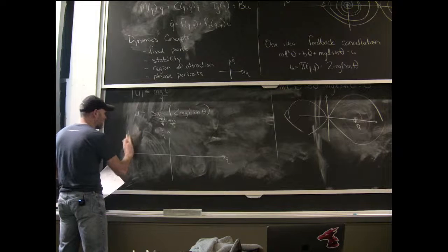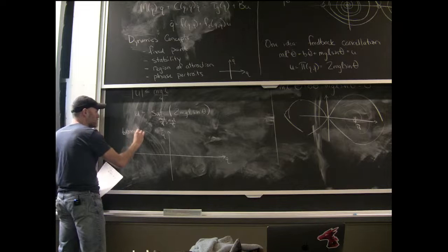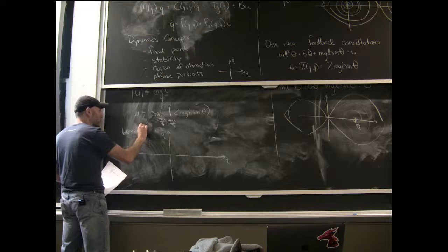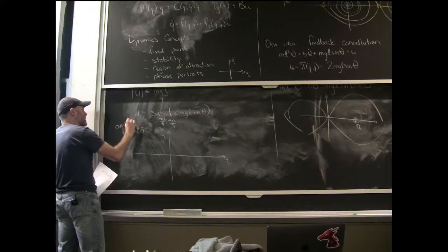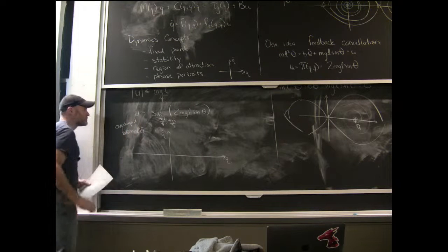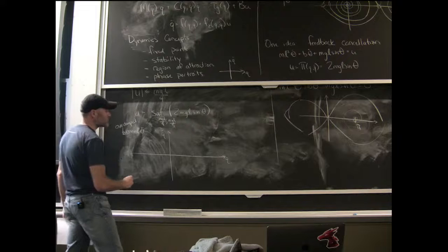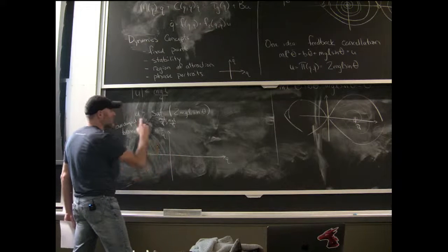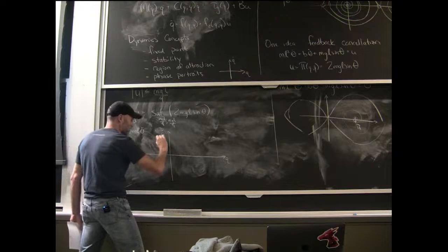So I want to say b theta dot dominates ML squared theta double dot, the overdamped regime, where I could draw this as just a first order plot. And I'm going to draw this now as the original passive system just looks like a sine wave like this.